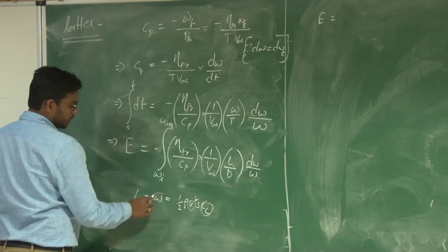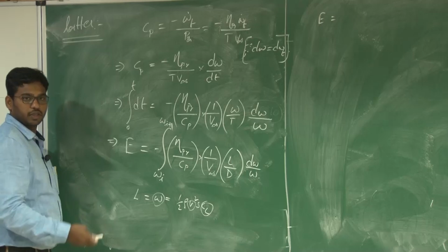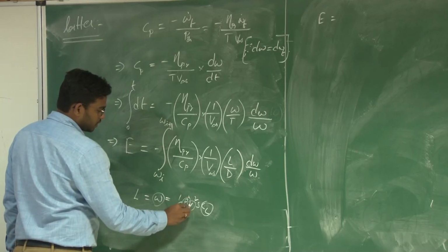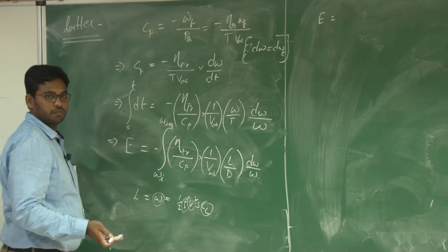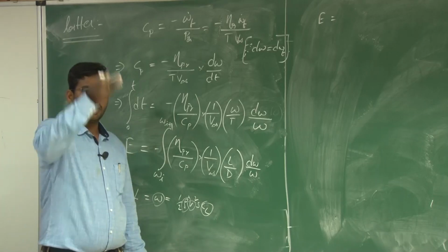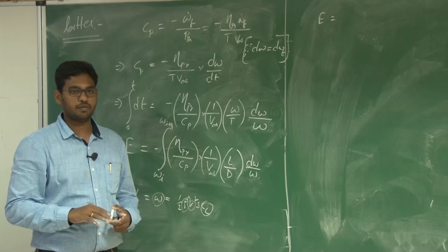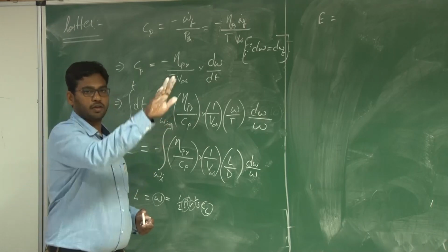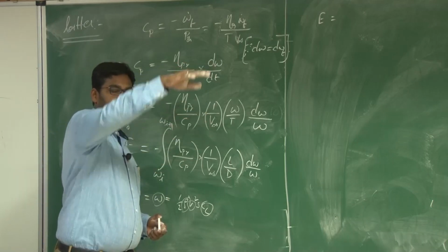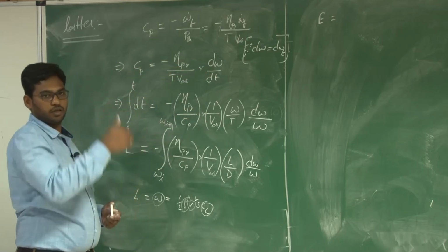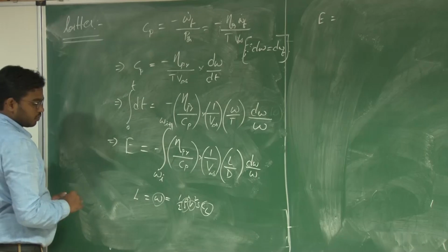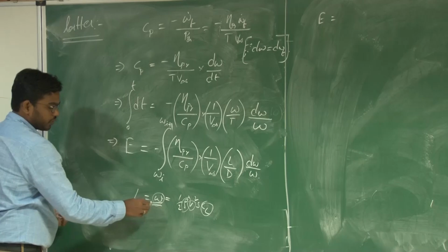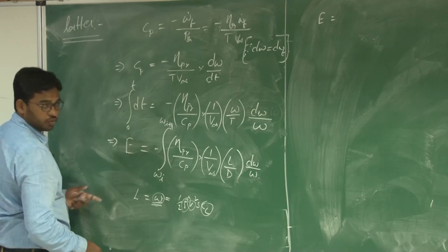And in that case, W is continuously changing because the fuel is getting consumed, right. The only variable that has to change is density. That means you will end up gaining altitude, which is known as cruise climb, right. Just like a balloon, you don't actually climb, but you keep gaining altitude because there is additional lift acting on the system, which is greater than the weight, right. Why? Because there is fuel consumption. We call it cruise climb.